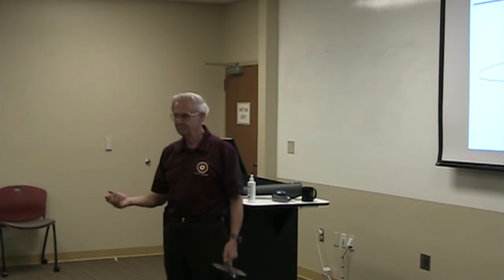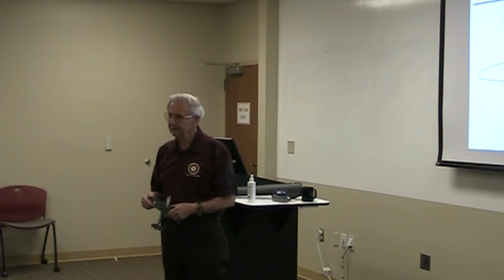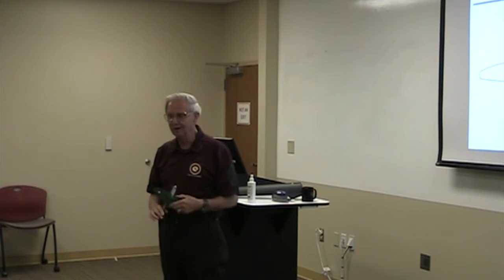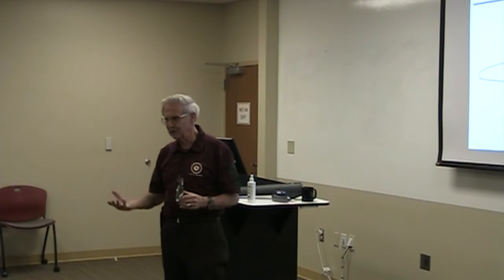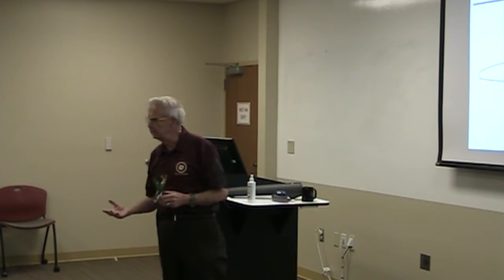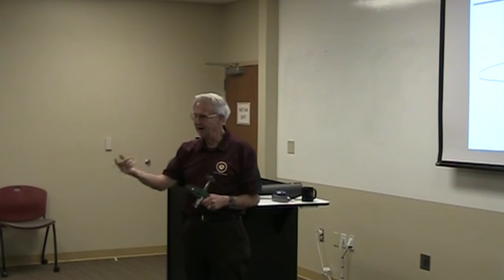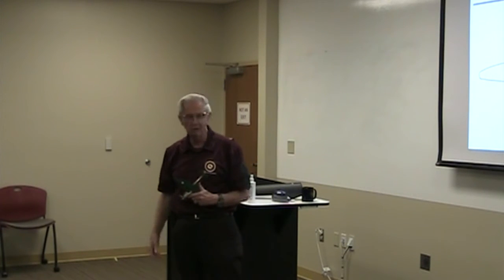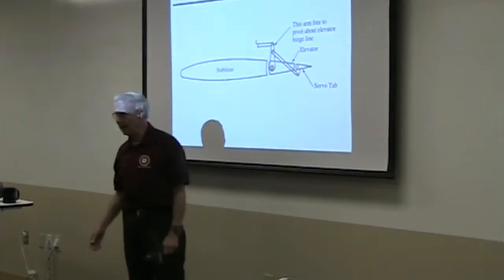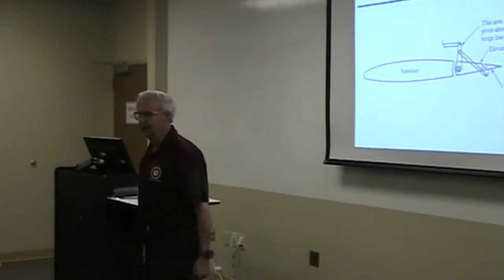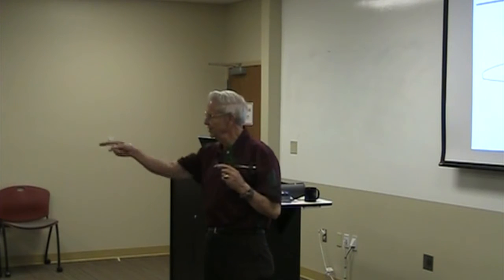Hydraulic brakes in the airplane industry is fairly recent. Even less, it's a little older than hydraulic operated controls, and of course now we're doing it electrically. Call it fly-by-wire, we're running electrons down the wire to a servo which moves the control. But this was a servo tab. The tab moved the control. On a B-17, that's how the pilots flew it. Was through this tab.